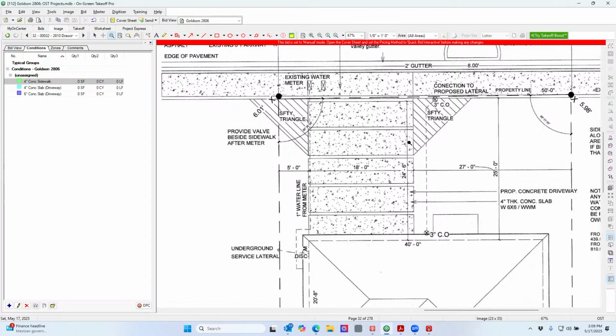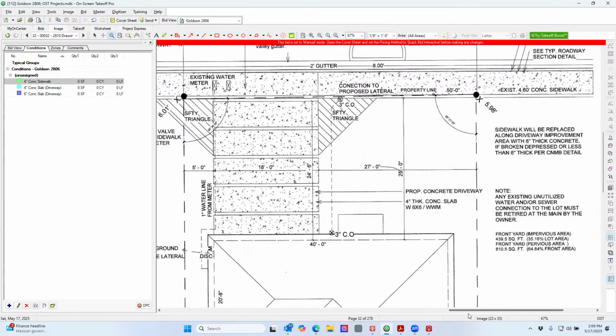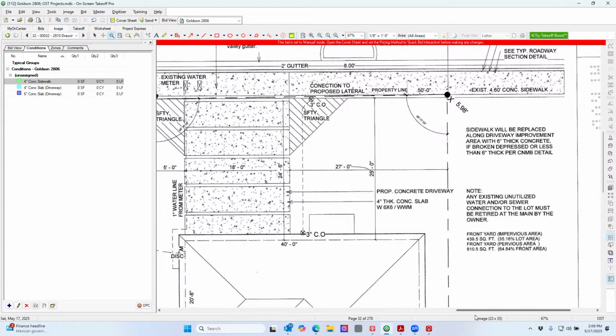Well, these lines kind of freak me out a little bit. I'm not sure what these lines are supposed to mean. See these lines in between here? It's almost like those are separate pads. Yeah, but that's very weird. If these were pavers and you were trying to do some type of architectural feature, that makes sense. But for a driveway like this, it's weird. So again, class, this is where we send in an RFI. And on this particular RFI you would send out, you would bubble circle that with those red lines. Absolutely. Write a question. Absolutely. Yes, please. That is exactly perfect. Boy, you all are learning fast.